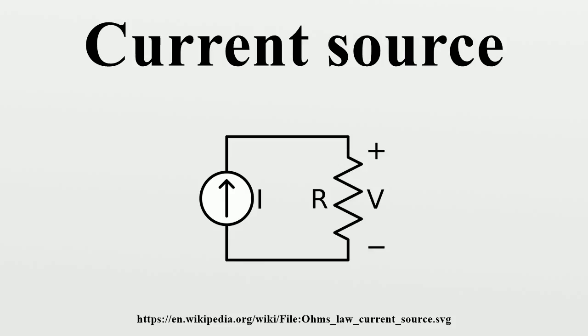In the two previous circuits, a decrease in VBE will cause an increase in voltage across the emitter resistor, which in turn will cause an increase in collector current drawn through the load. The end result is that the amount of constant current supplied is at least somewhat dependent on temperature. This effect is mitigated to a large extent, but not completely, by corresponding voltage drops for the diode D1 in Figure 6, and the LED 1 in Figure 5. If the power dissipation in the active device of the CCS is not small or insufficient emitter degeneration is used, this can become a non-trivial issue.